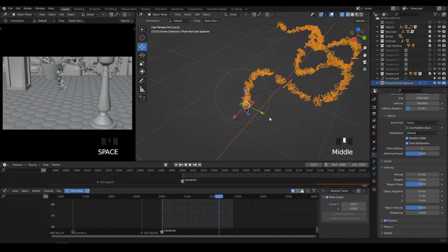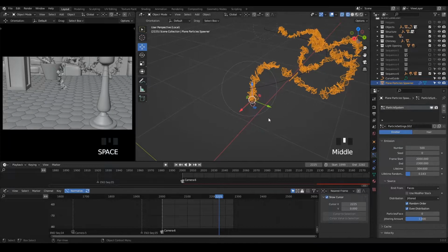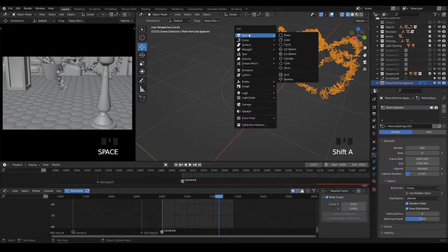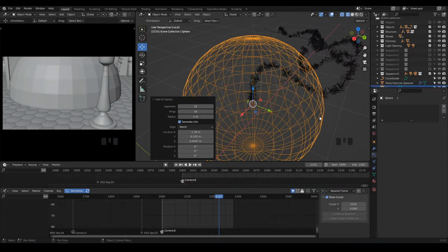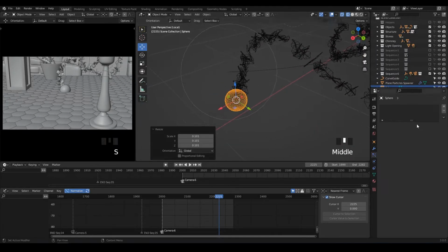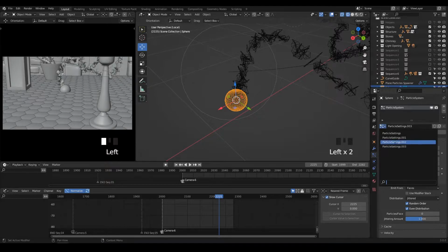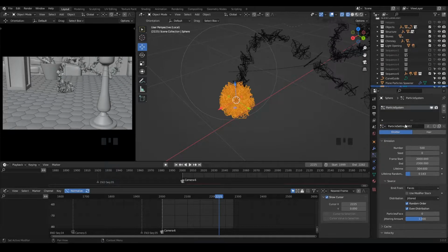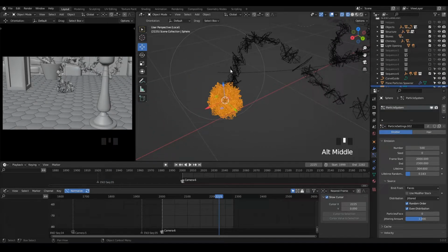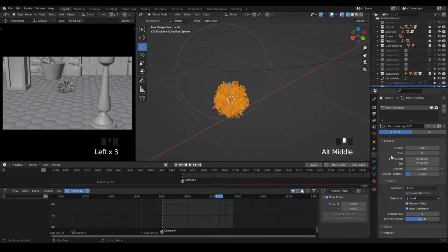What would be great would be, this is called particle system 002, meaning that if I add now a UV sphere and I scale it down like that, okay, I can add it to particle system 002, just like materials. So now I have this. It's the same as this one. I'm going to hide it.